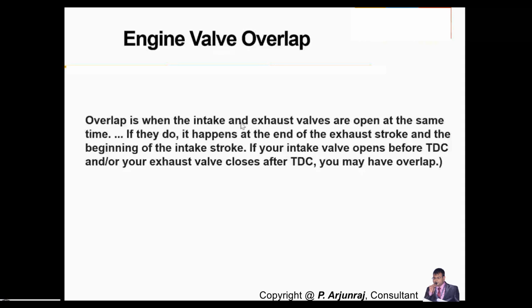So here it is nothing but the period between the inlet valve opening and the exhaust valve, which are kept in the open stage. I told you the exhaust valve will open during the exhaust stroke. Up to what moment is it going to stay open? That period you are going to have as the overlap period. And you see here, the inlet valve opening and the exhaust valve open happen at the same time, at the end of the exhaust stroke and again at the beginning of the intake stroke.